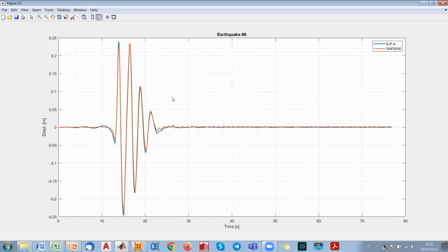And this doesn't happen for non-linear devices, because you have seen that for CSS and lateral ball bearings, we don't actually have many harmonic shapes and many subsequent cycles. We maybe have just a single harmonic wave. And this is something which is currently discussed for the revision of the standard code for testing, because maybe also for curved surface sliders there are tests, as we have seen in the testing protocol, and also in the first numerical laboratory, related to 3 cycles, and generally the number of harmonic waves that you can get from nonlinear time history analysis is just maybe 1 and 1.5. So they are surely different than 3.